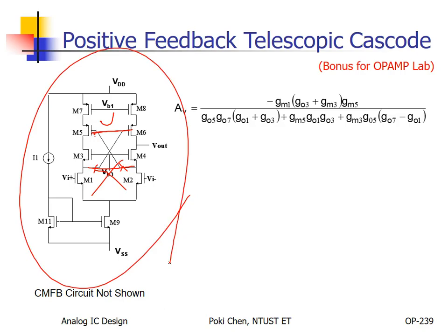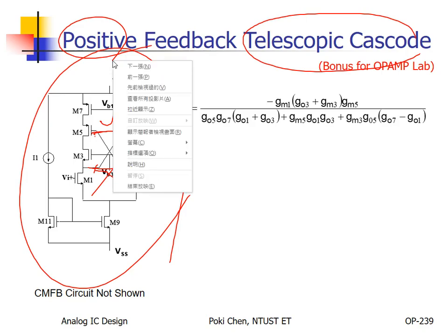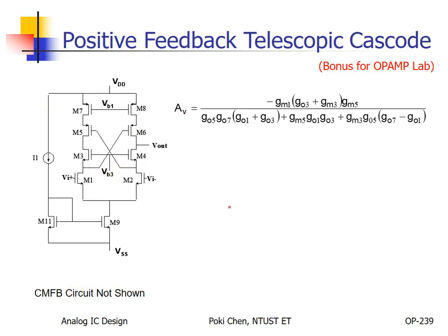It means what? For the circuit itself, it's almost the same as the previous one. But how can you achieve such kind of positive feedback? Again, some kind of cross connection. With the help of such kind of cross connection, you again achieve some kind of negative impedance for positive feedback. That is really interesting, right? Positive impedance can only be used for negative feedback. If you would like to get positive feedback, then you need to apply negative impedance. And the most convenient way to achieve negative impedance is by such kind of cross connection.